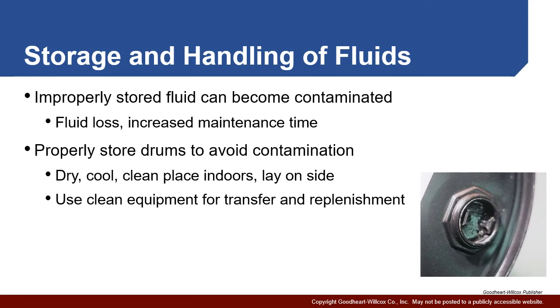While it's essential to maintain your oil in proper condition while it's in your hydraulic circuit, we also need to be concerned with how we store our fluids and how they're handled. The fact is, this is a big opportunity for our fluids to be contaminated. So it's essential that it's stored in sealed drums. The drums are kept dry and clean.